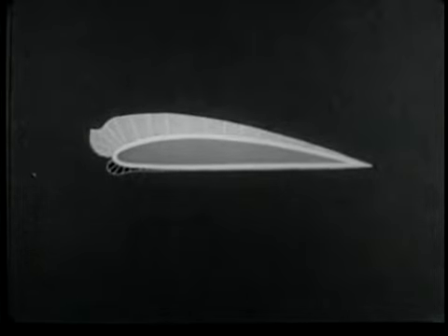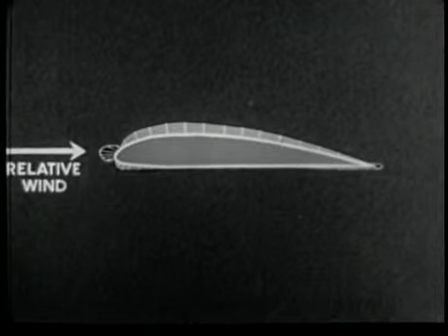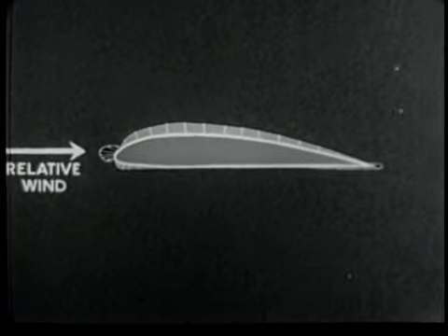An airfoil at rest in still air is at atmospheric pressure over its entire surface. It has been shown that airfoils derive their lift from the pressure differences acting upon their surfaces, the negative pressure difference upon the upper surface at normal angles of attack being the major component of the lift force. Now let us see what happens to pressure values and distribution at negative angles of attack.